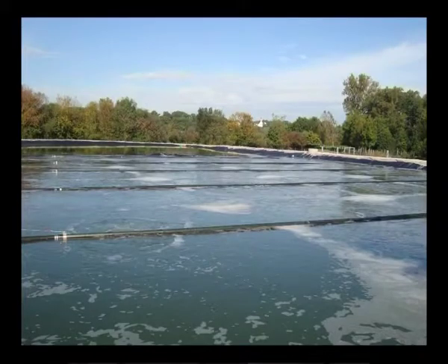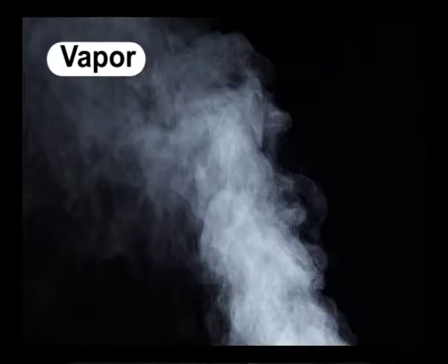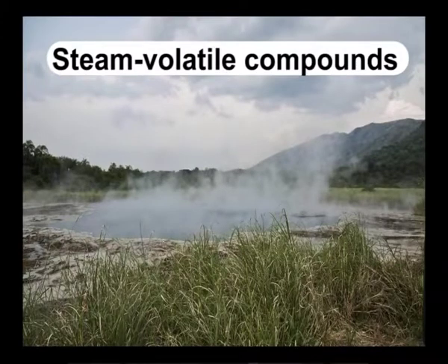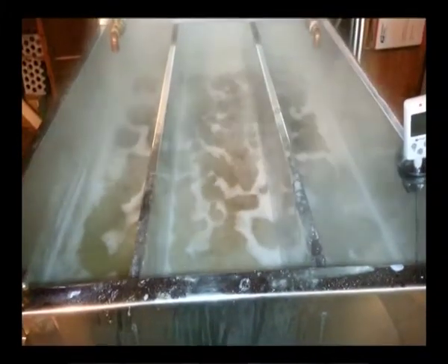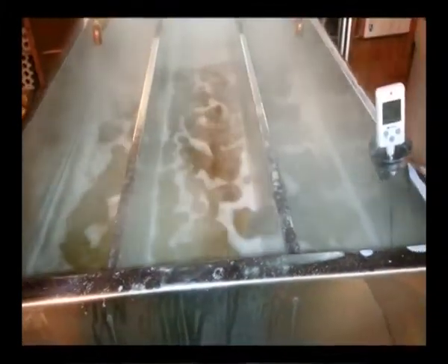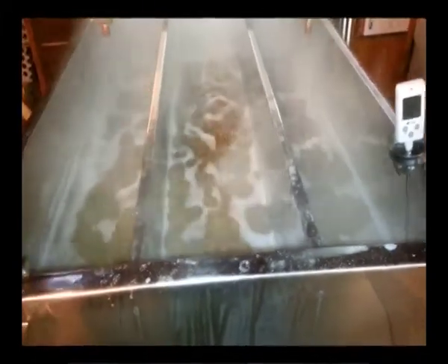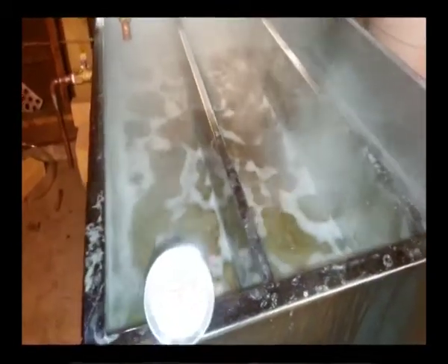Evaporation is a method used to concentrate non-steam volatile wastewater components. The evaporation plant contains a vapor condenser by which vapor and steam volatile compounds are separated from the concentrate. While the concentrate is then recycled into the evaporator, the exhaust steam can be used for indirect heating of other evaporator stages. The degree of concentration of the wastewater components depends on different factors.